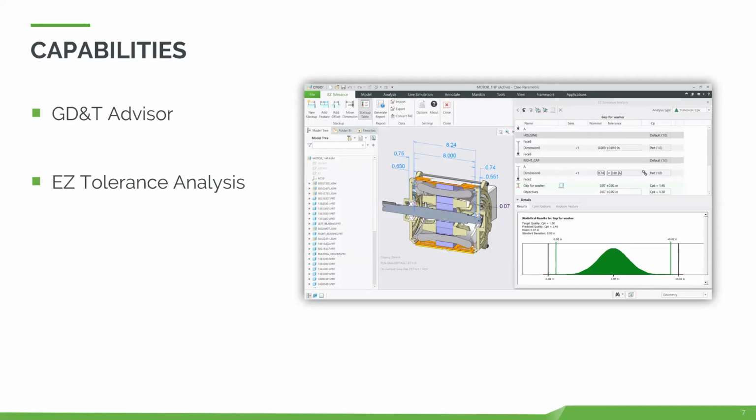This is something that we use for evaluating the impact of tolerances and dimensions in the design. We're able to do that right in the product well before it would ever go out for manufacturing. And this is something that we play in with our 3D annotations. So you can look at different statistical results, potential defects, worst case scenarios, RSS, even which annotations have the highest contribution to the goals that we're after in the model. So all things that are very useful.